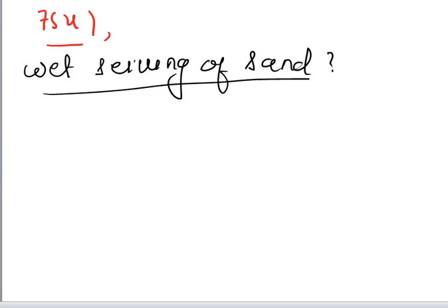So if there is fineness in sand, that is, there is some fraction of clay and silt also in that sand, then what we need to do is first of all wash the sand under flowing or running water such that the sand gets segregated from the silt and clay portion, and the silt and clay portion is washed away so that we get the pure sand, not the impure one. And then after that we will do the sieving. So this is the basic objective.